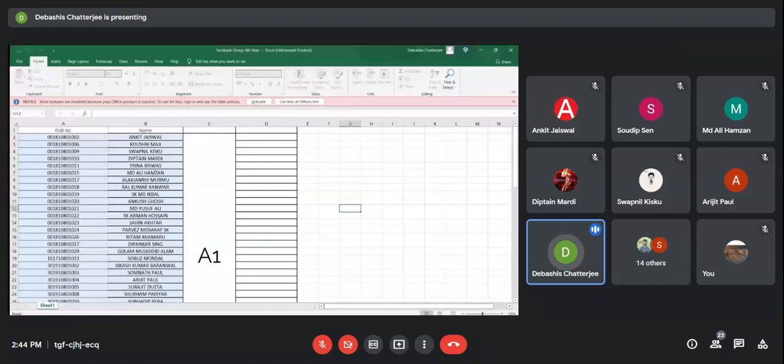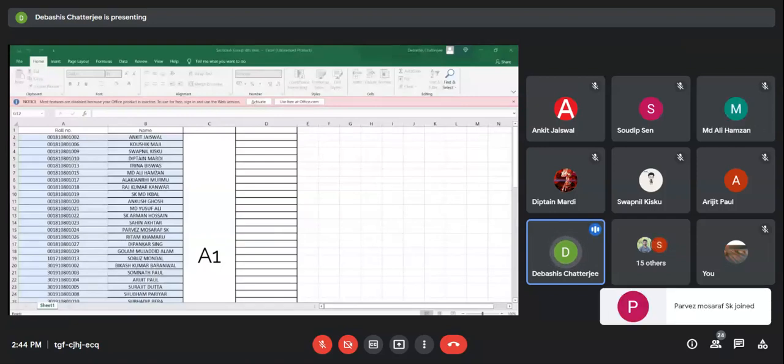So this machine will be intended for small scale induction generator application. We will see that later on, but before that you should design it first. So 3-phase 110 volt, 50 hertz, 750 watt, 735 RPM, 0.8 power factor tentative, and you have 45 degree temperature rise above ambient.